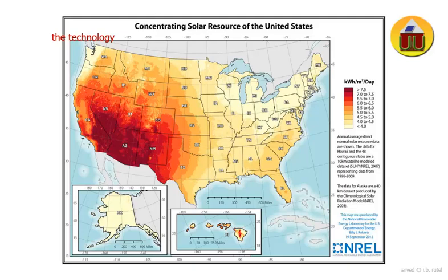For context, the average household uses about 1,200 kilowatt-hours per month, which is about 1% of production given by this single panel. So you may be tempted to think that over a 30-day period you would be able to produce 30% of your household use with just a single panel.